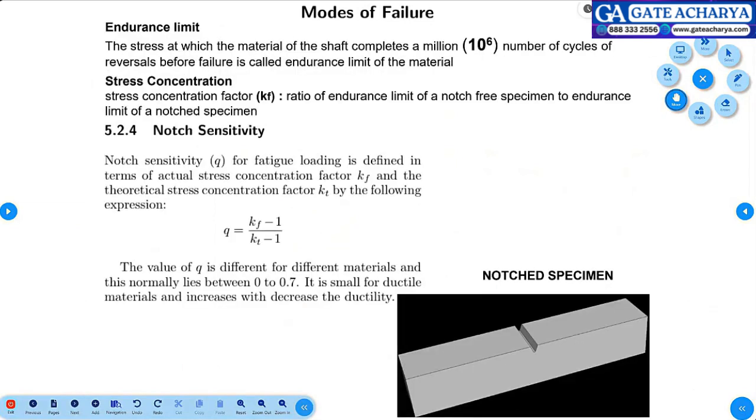Right. So you need to understand each and every material cannot be free from voids or cracks. Any raw material will always have voids and cracks. So if you give some varying loading, it will fail so miserably. In this crack region or void region, the stress calculated will not be as per your formula. The crack or void diameter is so small, and this diameter is sitting in the denominator. Anything divided by 0, what will happen? Undefined value. So stresses will reach very high values, and all of a sudden that will lead to failure.